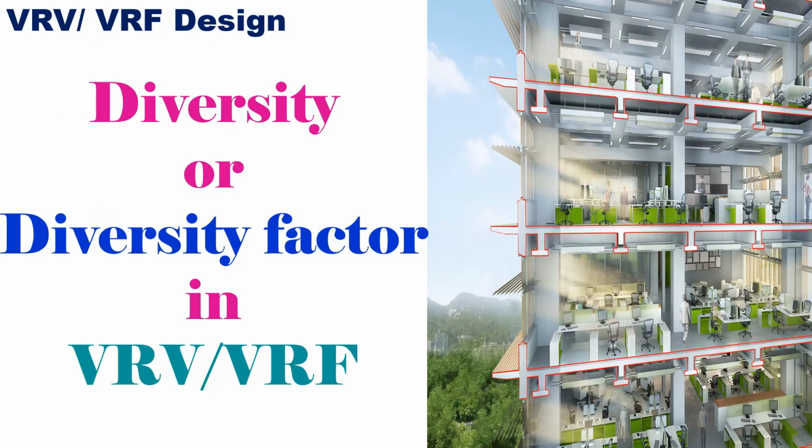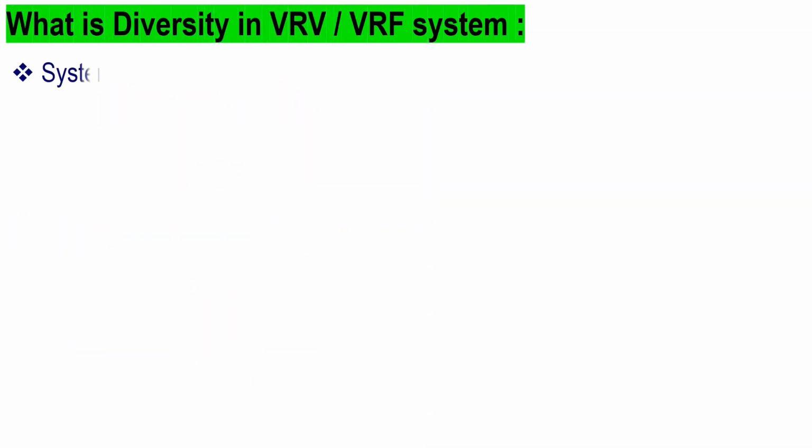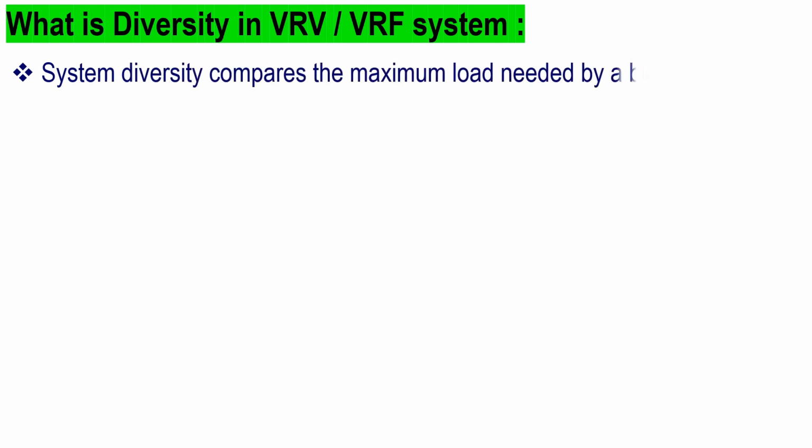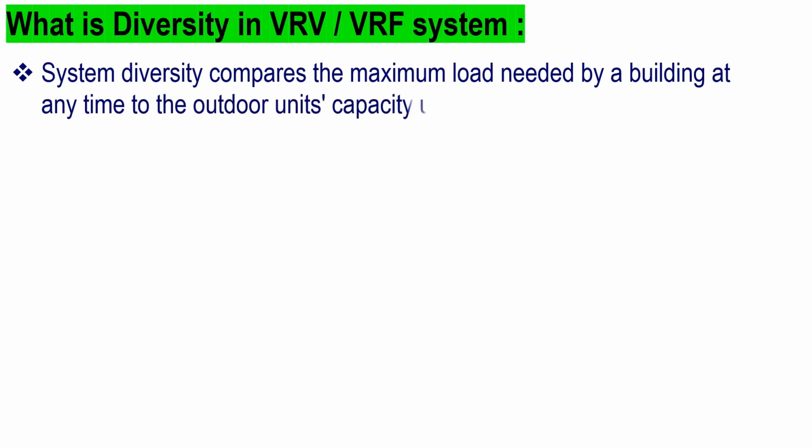Now, we will go through the third important key design parameter in a VRF system: system diversity and diversity factor. What is diversity in a VRV or VRF system? System diversity compares the maximum load needed by a building at any time to the outdoor unit's capacity under ideal